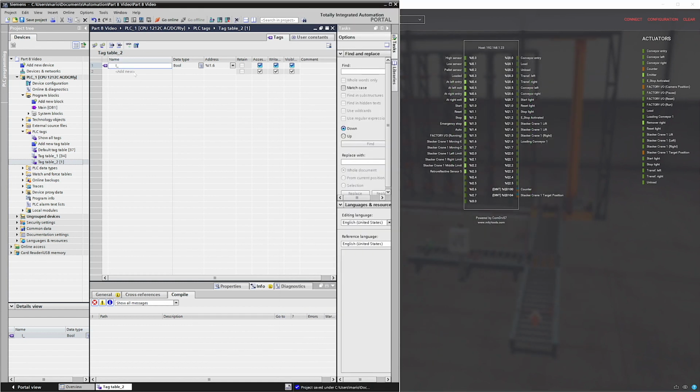And we'll name the inputs in the tag list I_S_crane followed by what they are. So the first one would be MOVX, and the address is automatically assigned as the next available input, input 1.6.